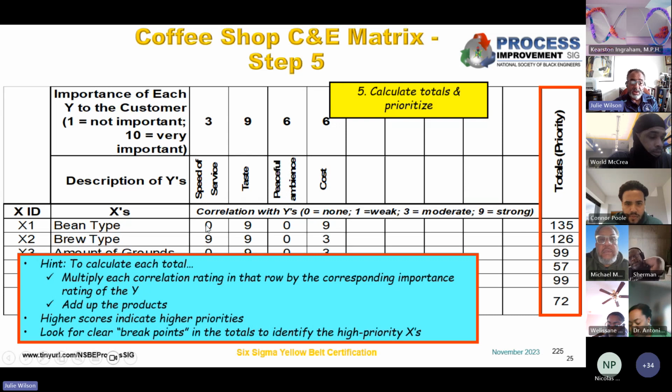If this does fail, how severe is the consequence? What is the probability of failure? How likely is it to fail? And third, what is your ability to detect that a failure is coming? So you have a scoring system where you assess the consequence of failure, the probability of failure, and the ability to detect your failure before it comes.